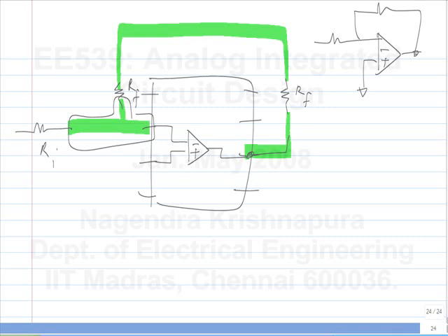So if you get an opportunity to lay out an op amp, this is what you should use. And similarly, even in an IC, when you do layout, this is the thing to do, right? You have to absolutely minimize the capacitance from the inverting node to ground, because it's going to just introduce extra phase shift and take you towards instability. Okay, so you have to first of all minimize the problem that you have before you start fixing it.